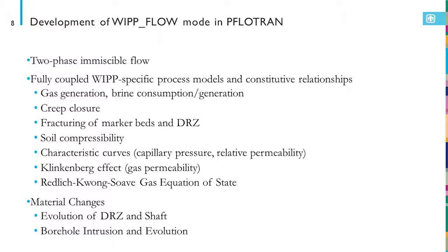Additionally, the ability to change material properties at any specified point in time was added to PFLOTRAN, and that capability is used to model evolution of the disturbed rock zone and the shaft properties, and also to model borehole intrusion and the evolution of the borehole properties through time.